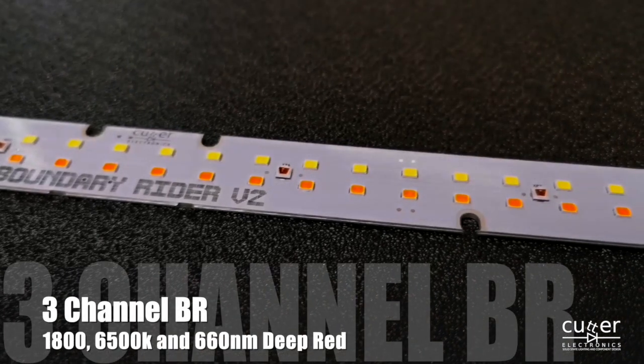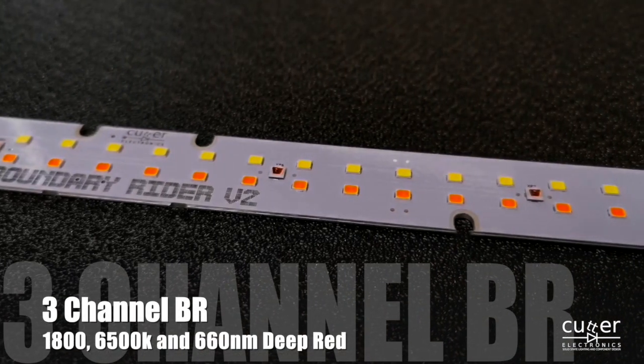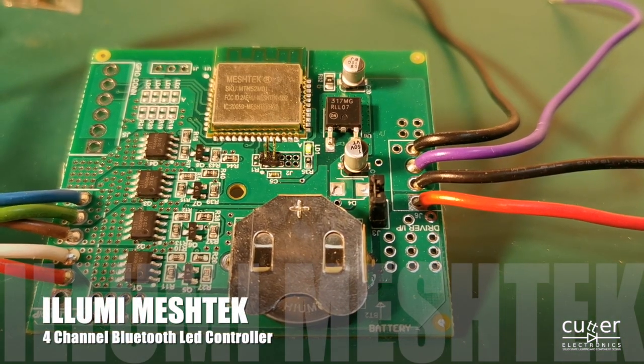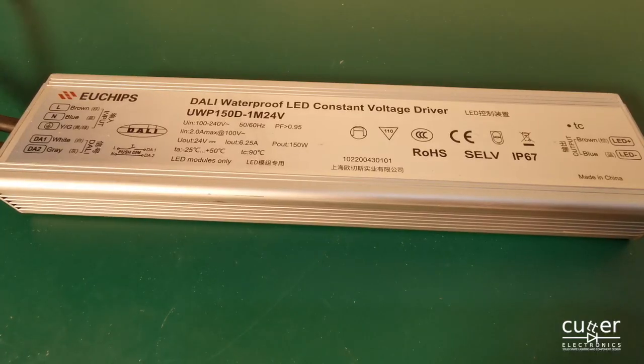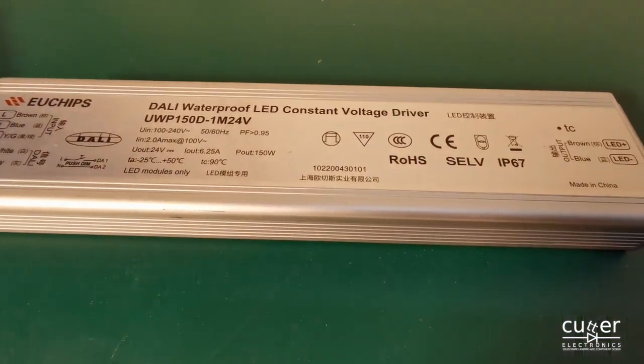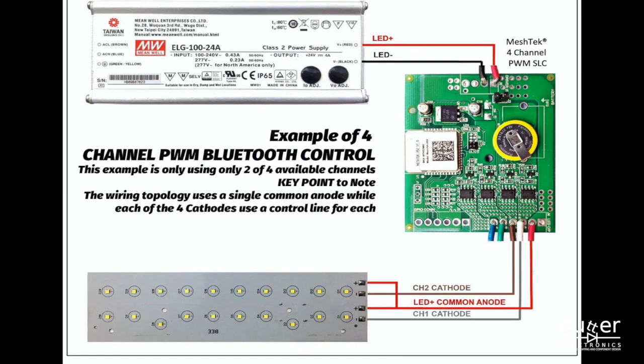The parts list: we will use a single 3-channel boundary rider board, a single Meshtek controller board, and a single 24 volt AC to DC constant voltage power source. The last item, the 24 volt power supply, is important to note here, as we will be driving 3 channels of colour, but doing so from a single power supply.